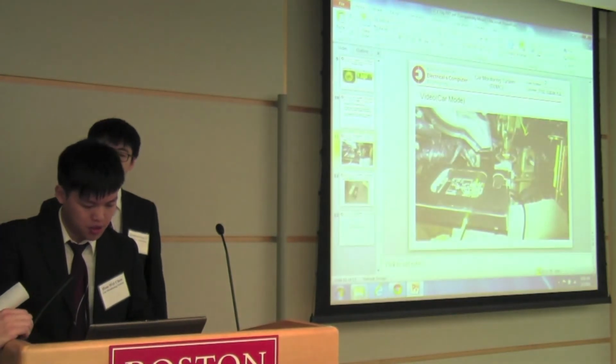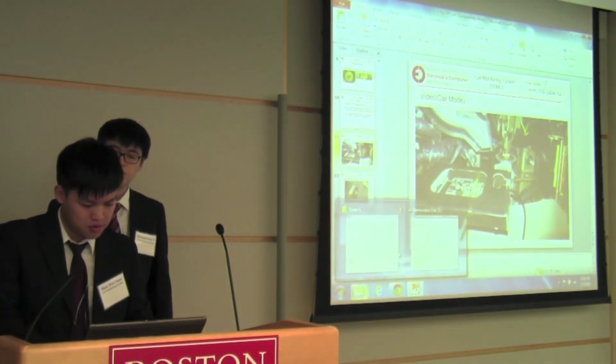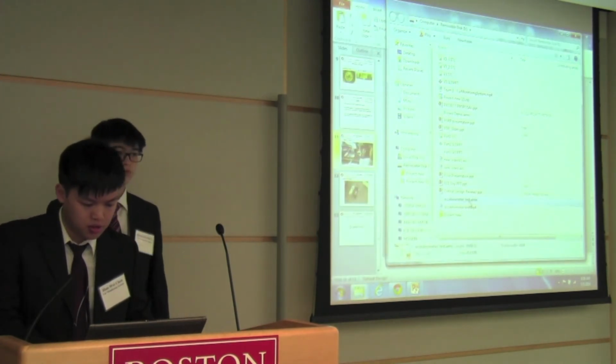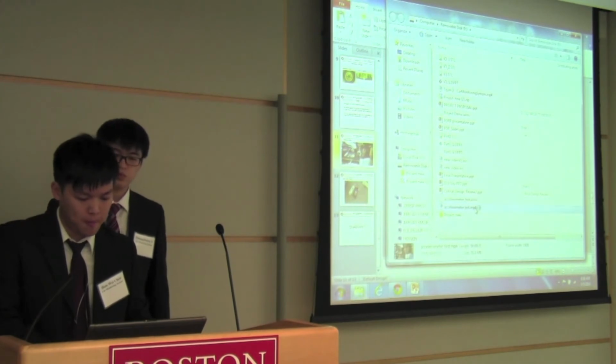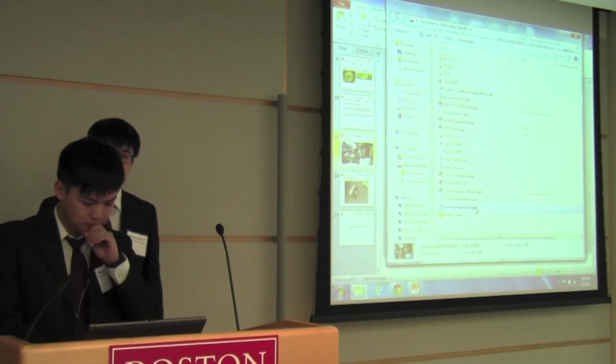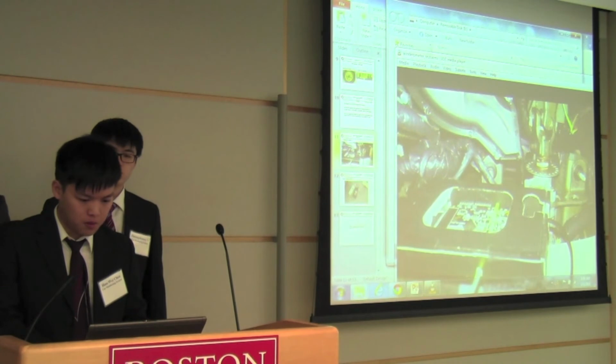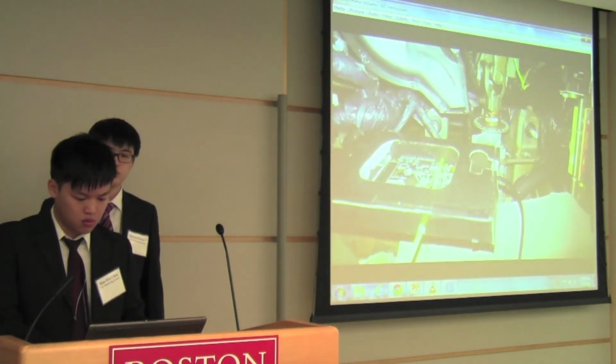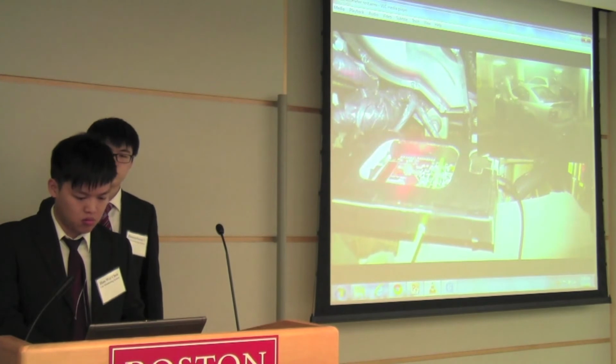The first video we're going to show you has dual videos. One is of the development board that's plugged into the OBD, and a little window pops up of me outside the car, either aggressively closing the door or going back and forth. The green light just means that the system is activated. Red light means the door is closed, and blue light means the door is locked.